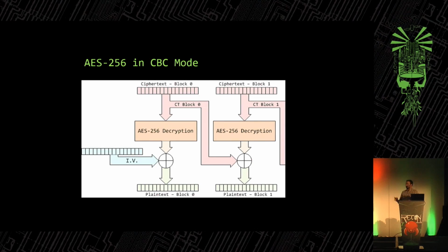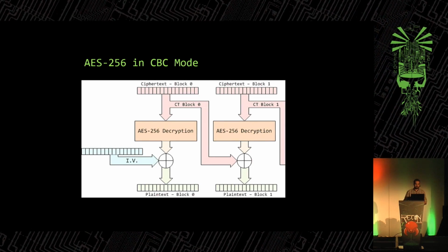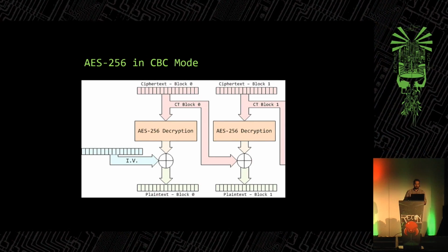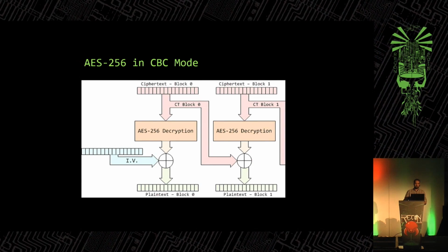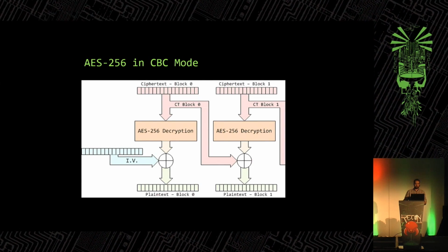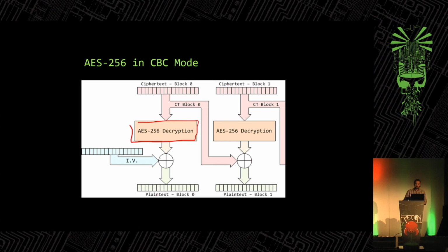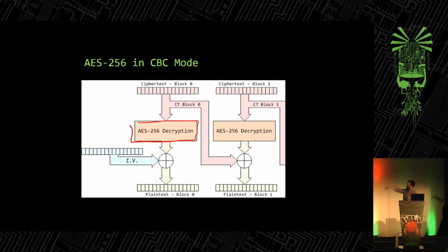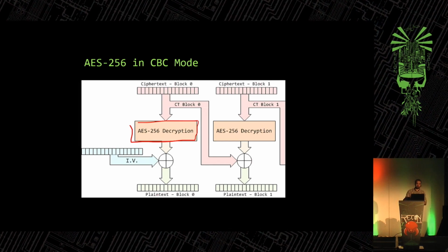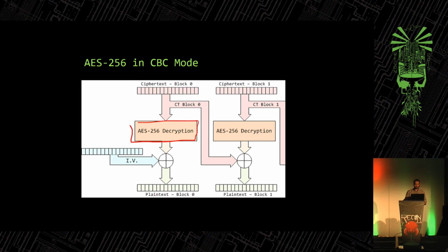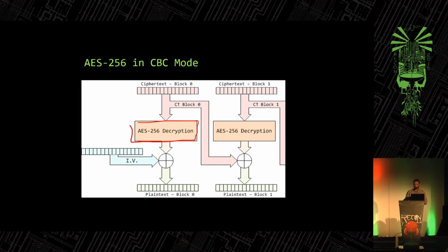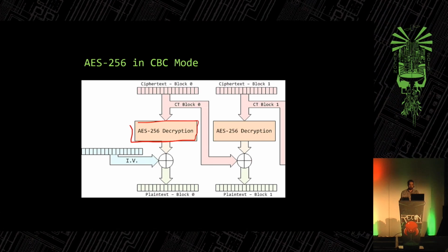And so this is great because we can do a side channel attack now, because we have this situation. We have the input ciphertext here, the AES 256 decryption in the center, and after the decryption, it's applying the IV. So we don't even care what the IV is, at least initially. We have everything we need to do the entire side channel analysis.